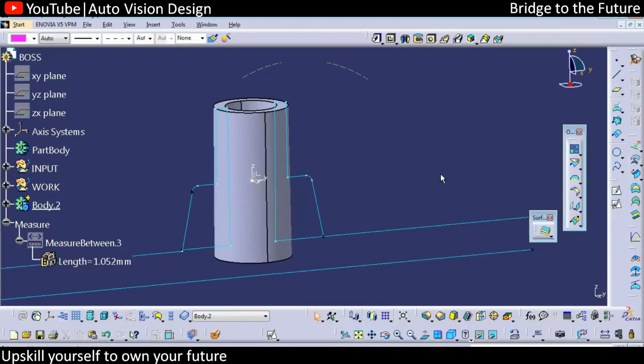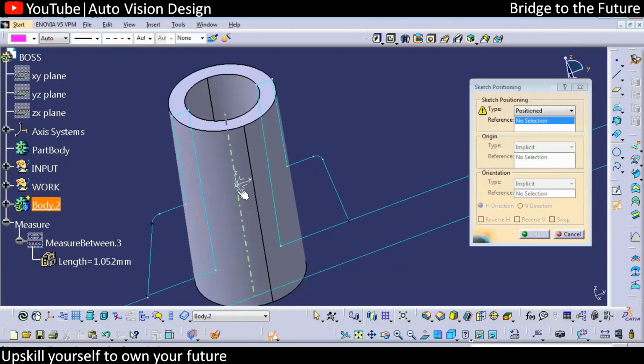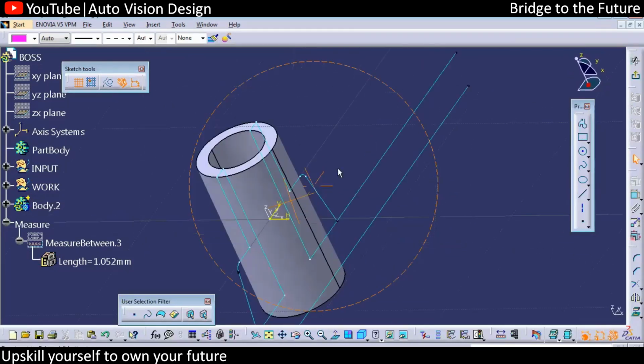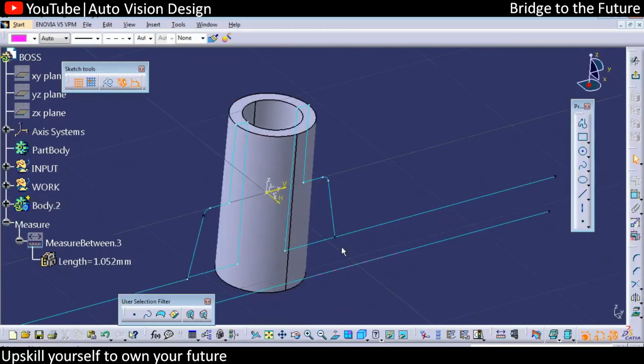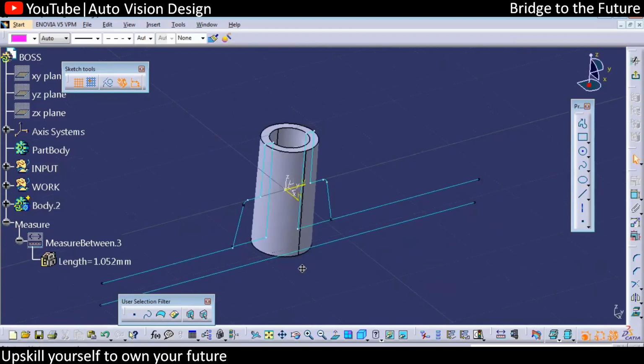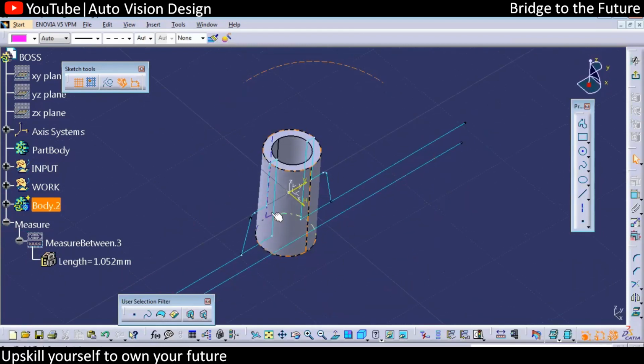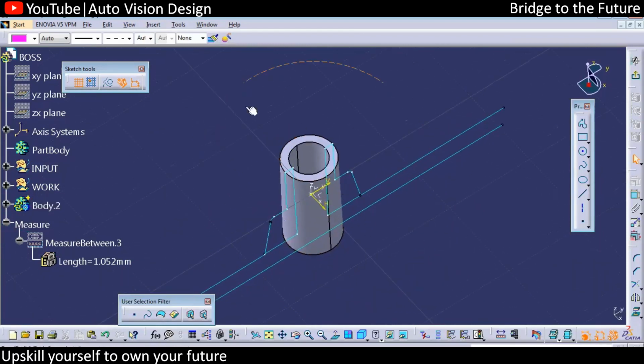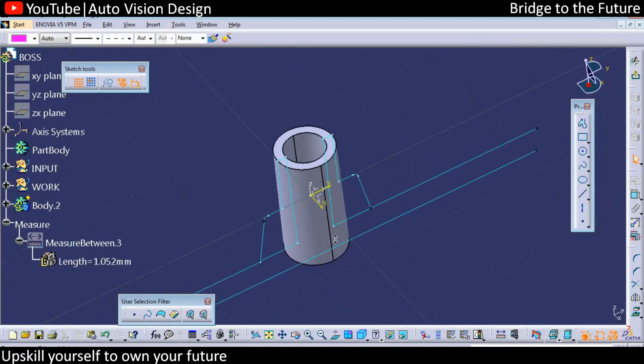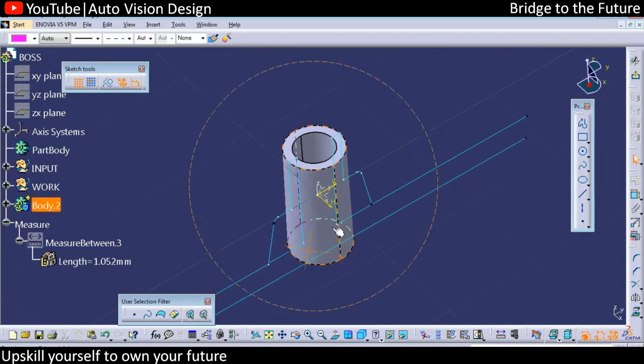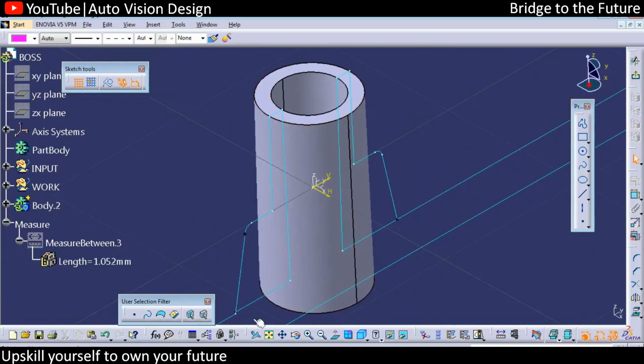Again we need to create a sketch. We add the sketch on the same plane. Always go for the position sketch, and with respect to that we can select the point. And always make sure that when we have given the sketch or master section in one direction, if the part is circular, it will be the same in the opposite direction. If there is any deviation in the opposite direction, they will give two planes, whatever that section, they will give both sections.